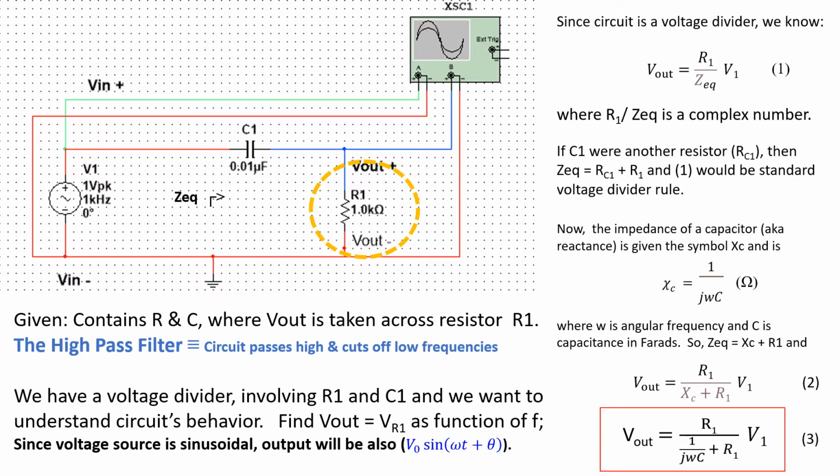The formula in blue font at the bottom of the slide shows the mathematical form of the voltages being considered in this demonstration. Since the voltages are sinusoidal, we'll be calculating and measuring three different properties of this formula, and these are amplitudes, frequencies, and phase angles. Now, the amplitude is typically written as the capital letter A, but I substituted V0 to reinforce the concept that we are dealing with voltages. Frequency is captured in the omega term, and the phase angle, of course, is the theta term. We'll go into all these elements in much more detail.